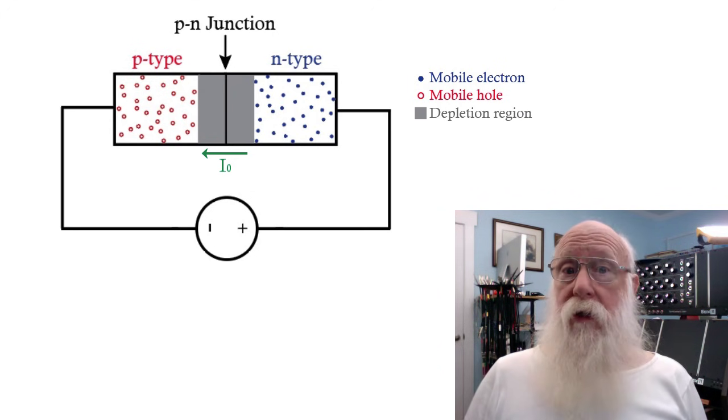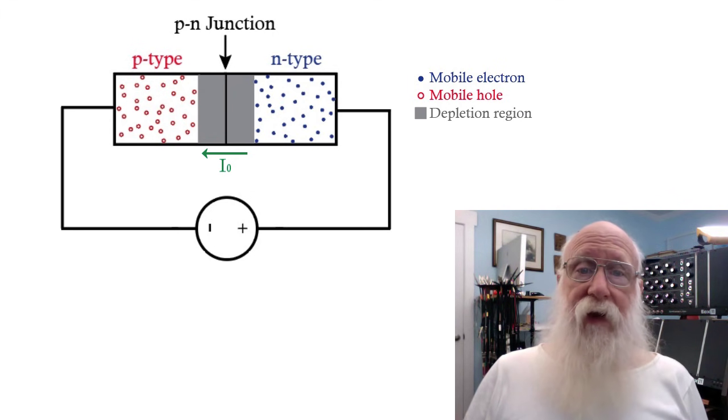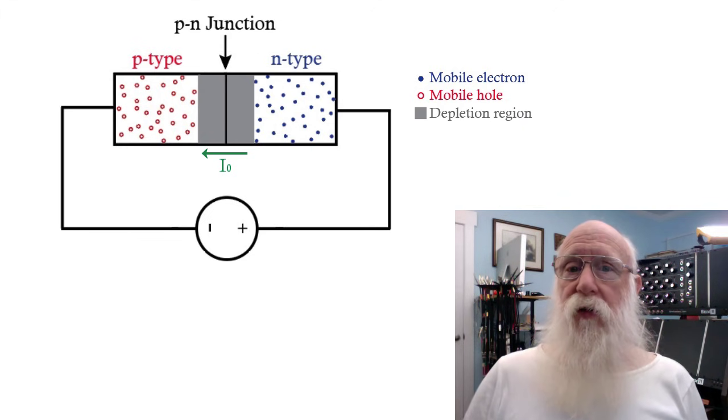Now, where does the noise come from? Well, the thermal effects that knock carriers out of their orbitals so that they're free to move, first of all, is a random process. It doesn't happen uniformly. You don't get exactly the same number of charges knocked out of orbitals every yoctosecond, and the collisions of those carriers with other atoms, thus freeing up more mobile charges, is also random. So what we've got is this tiny little noise signal. Now this noise signal does have the properties of white noise. It does have a fairly flat frequency distribution, at least at reasonable frequencies.